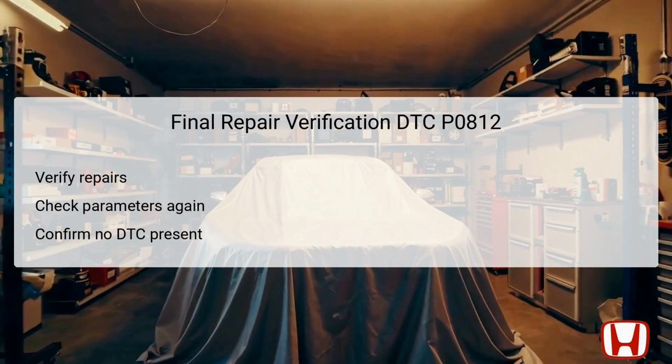Make sure to inspect that the ATR switch status reflects as on under operational conditions, confirming functionality. Additionally, ensure no DTCs are present at this stage to validate that the repair resolved the original issue. Finally, documenting these steps and confirming any repair work helps maintain a detailed history for future diagnostic assessments.